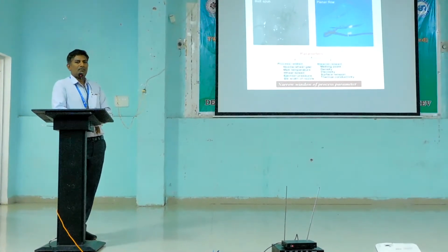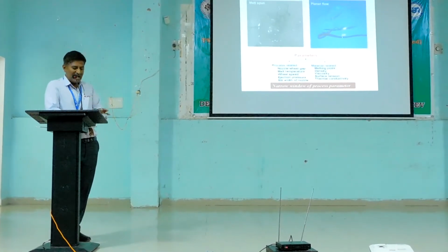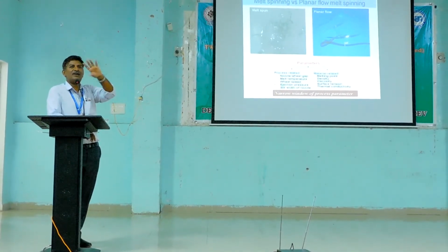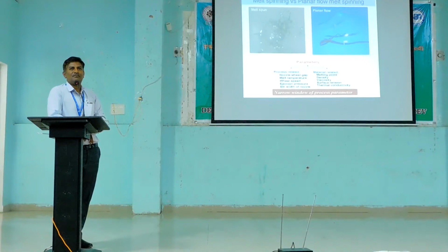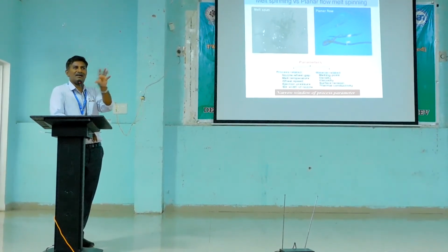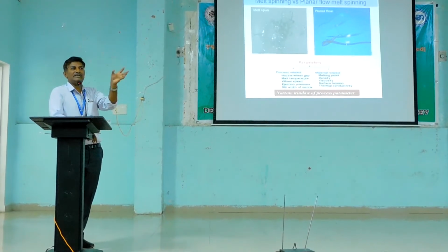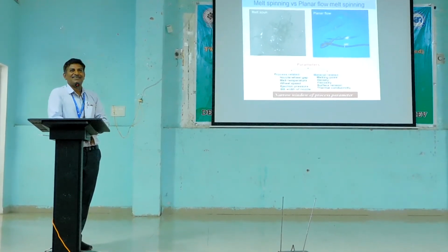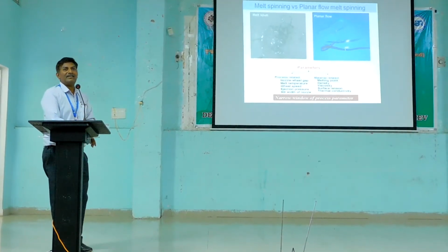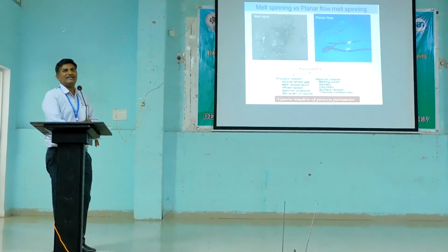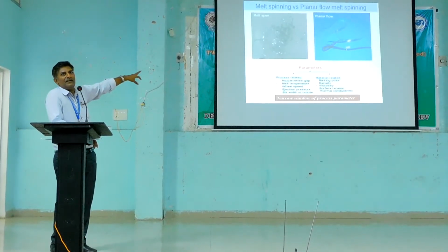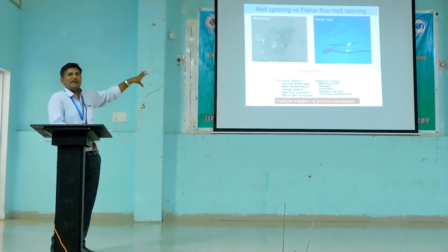Now, have you come across this? Just go around somewhere and see. Now there are no CRGO transformers. What transformers are coming in the market now, in many places you can see, it will be written amorphous. You must have seen that. Earlier it was a very rare thing, but now in many places you see they write amorphous. That amorphous transformer has this material, these metallic ribbons.